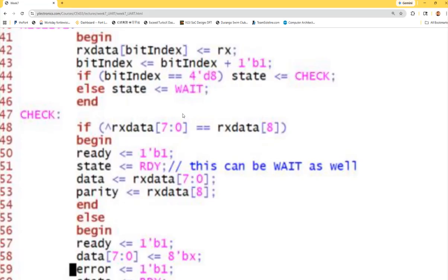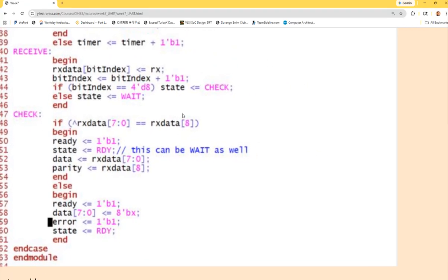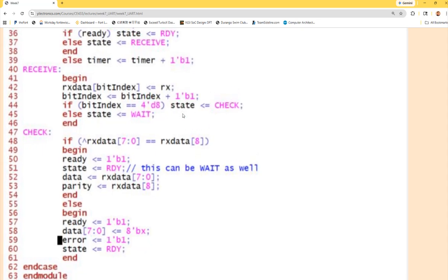So it's question number 1 in the in-class. Which line of the code will get you the parity bit of the 8 bits received data? So from the receiver's module, this is a vector, right? And Verilog allows you to directly put an XOR operator in front of the vector, and it's going to do a bitwise XOR of all the bits.